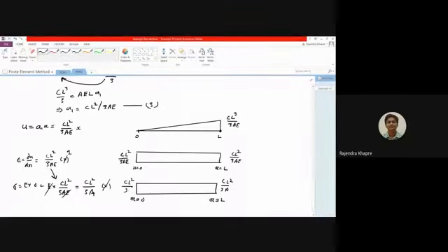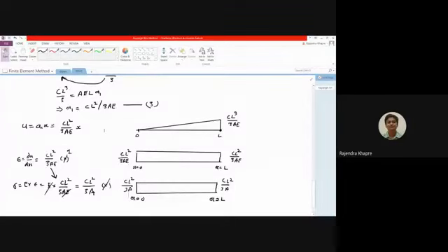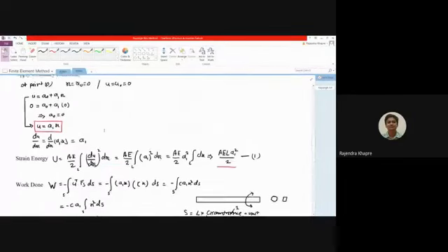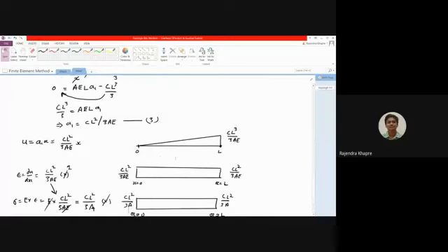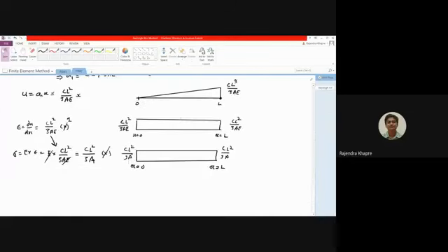So you see, if you consider this polynomial, I'm going back over here, that is U is equal to A0 plus A1 X, what you are going to get is this one. So this is the variation of displacement, this is the variation of strain, this is the variation of stress. Now you just understand that the stress is constant throughout the length. If there is a point load acting at the end of the bar, in that case the stress should be constant.